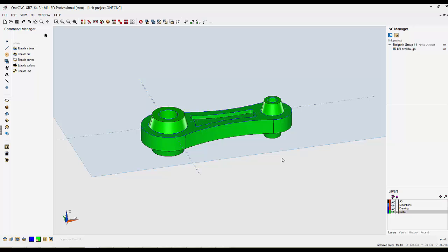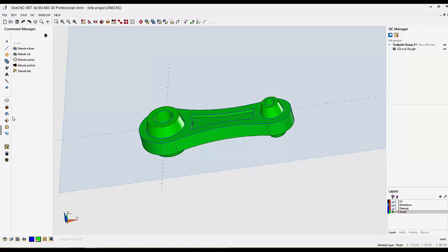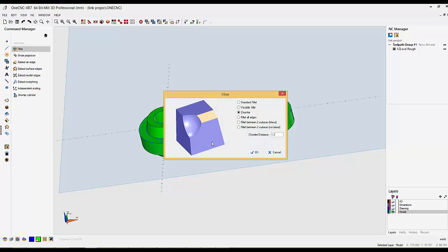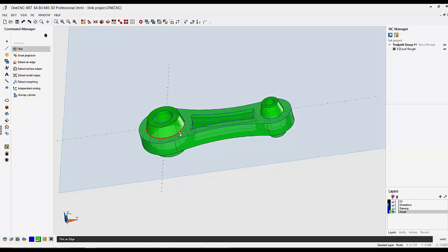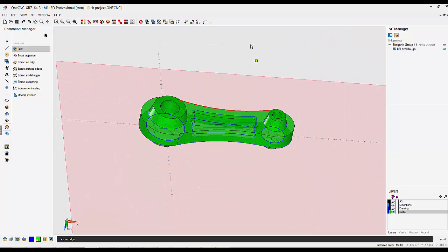As you saw on the main drawing, it had a fillet radius typical of 3.175. So we're now going to go and use our model tools. We're going to fillet. We're going to give it a standard fillet of 3.175. And what we're going to do now is digitize this model. We're not picking up on the geometry here, we're actually picking up on the intersections. You can select as many as you like. So I'm going to do around all the bosses and around the pockets. So I'll just turn it over, make life a bit easier, and we can left click on all of those